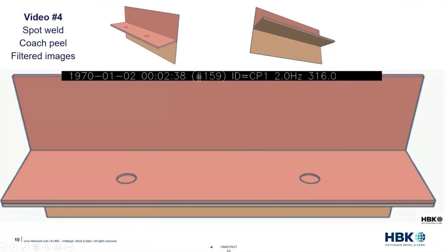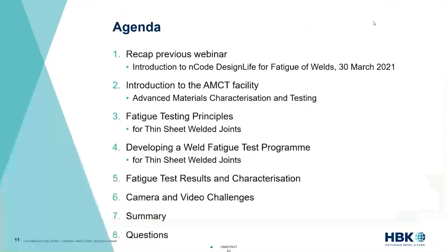This presentation will show how we develop these weld specimen geometries, develop the fatigue tests, and reduce what is gigabytes of images and videos into small presentable videos that can be used in a presentation like this as a summary, and how we use these to verify the failure mode and combine with the stiffness drop analysis for characterization and reporting.